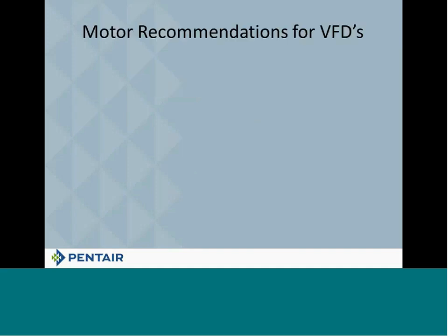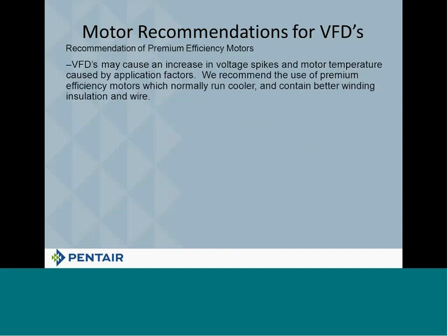So, motor recommendation for variable frequency drives. We've talked about Bernoulli's law. We've talked about the affinity laws. Now let's get into the drives themselves. We're going to recommend for above ground pumps that you use a premium efficiency motor. What a premium efficiency motor does is it builds in a little extra service factor that it doesn't tell you about. Okay? So premium efficiency motors are going to have a little more oomph in them, and you can abuse them a little bit more and not bother them quite as bad. All right?